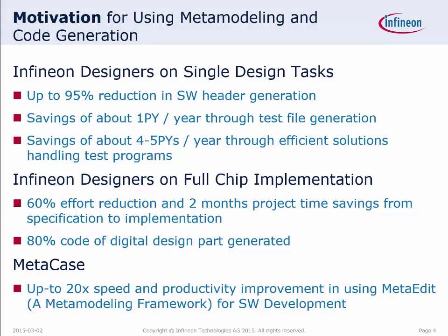Also the software team was using this firmware header file generation. Then the system level team, using transaction level modeling and creating virtual prototypes, used again the same specification to generate their SystemC register code and SystemC top-level connectivity.